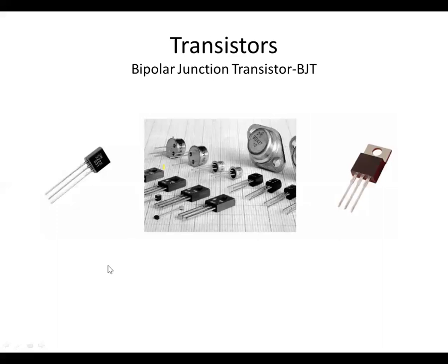And you'll find transistors in a lot of different types of packages, very small ones, the metal cans like this. This is typically a power transistor, and the purpose of it being in a metal case like that, and also this packaging where the transistor's mounted in this ceramic container, is the idea that you bolt these packages to some sort of heat sink to help dissipate power.